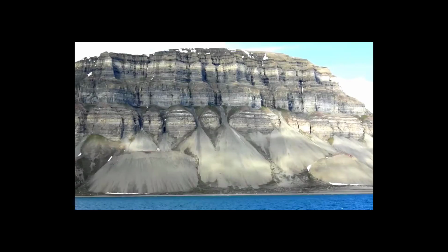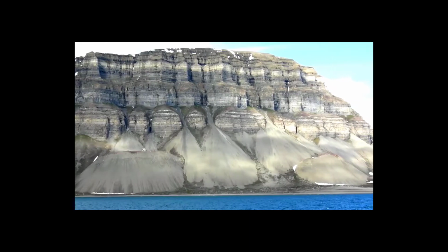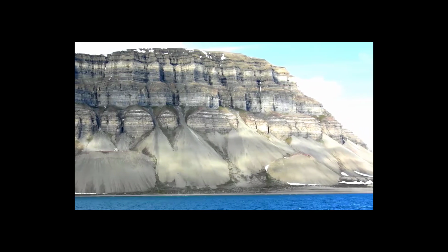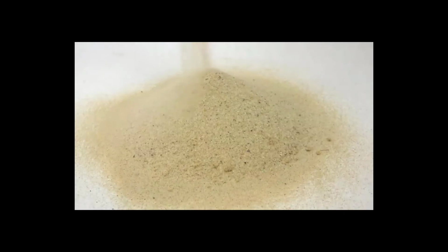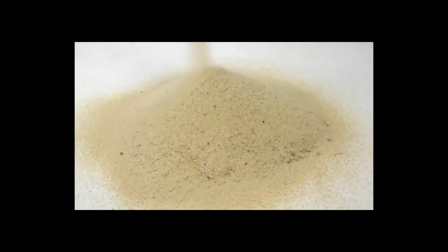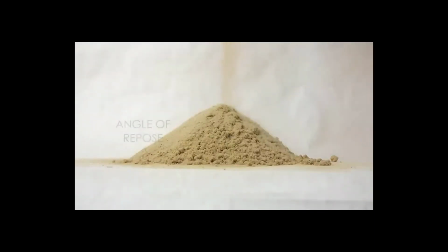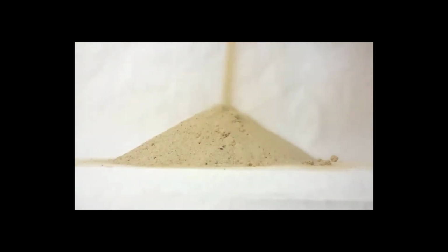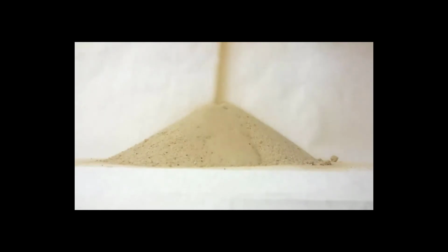This is why granular materials generally can't stand vertically. The weight of the material itself is enough to cause a shear failure along an angled plane. Pour out some sand on a table and you'll notice that the pile forms a slope. The angle of this slope is called the angle of repose, which is the steepest angle at which a soil can naturally rest. In other words, this is the slope at which the shear stresses within the soil, due to its own weight, are exactly equal to the shear strength caused by the internal friction. Any steeper and the soil will slide.